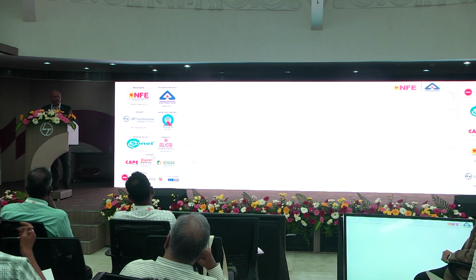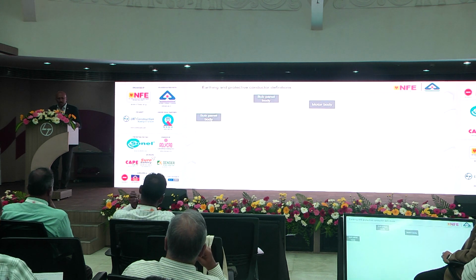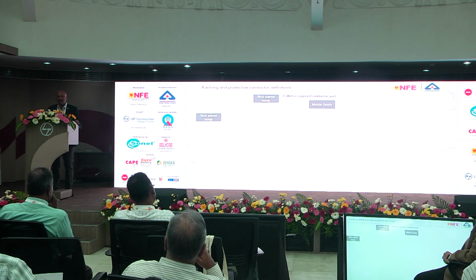After seeing my picture, you should think whether this exists in your building, whether this exists in the buildings which you have designed or erected or tested. If it is not there, you can be 100% sure that the building you have done doesn't have any safety. So don't think that you made a safe building. Now, protective equipotential bonding. Your building will have exposed conductive parts. You can find this explanation in IS 732, clause number 4.2.11.